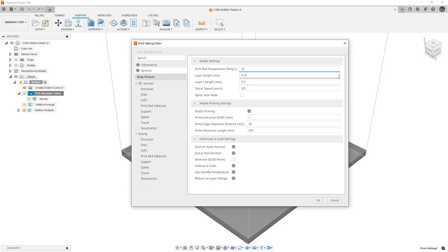Next is going to be the layer height, which is a direct indication of quality. Now, if you're using a slicer that came with your 3D printer, more than likely this layer height is going to be driven by a quality setting that you use. Now, this layer height at 0.15 should give us pretty fine detail, but note that we also have individual control of that first layer.